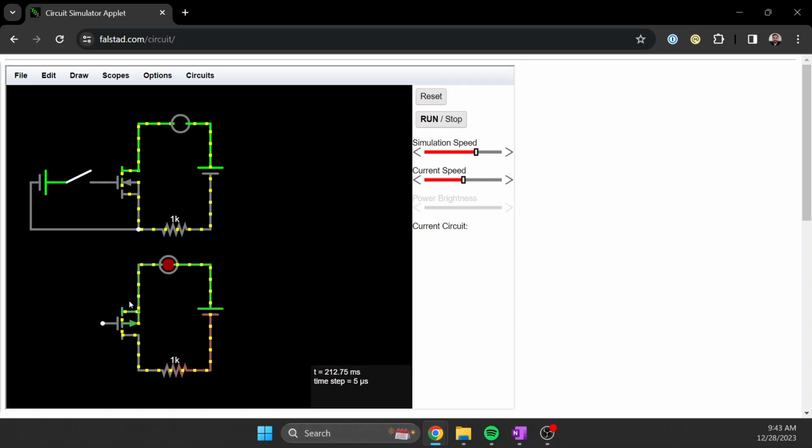It'll create this bridge through the gate naturally when there's a lower voltage at the gate than at the source. And that's how this is all determined. Here, if the gate voltage is higher than source voltage, it closes this connection and causes current to conduct. Here, if the gate is less than the source, it conducts. Here, the gate has to be more than the source.